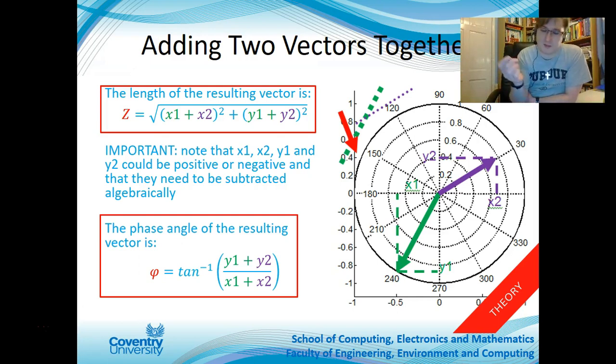That's an interesting point as well with complex numbers. If you wanted to use a mathematical package like Wolfram or MATLAB, you have to make sure that you use the i terminology, because that's how mathematicians represent it. Unfortunately for us, i represents current, so engineers usually use the term j to represent the imaginary unit. Be aware of that.